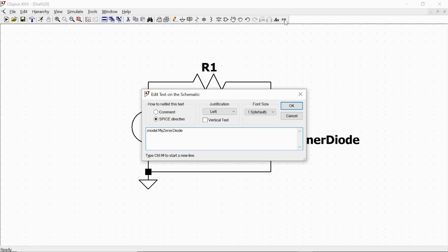The type of the component is the diode, so we say D. And then in between parentheses, we define the parameters of our diode. In some parts, they will be the same as the junction diode that you've seen in the previous tutorial. So for example, Ron equal 0, Roff equal 1 megaohm, Vfwd equal 0.7 volt, and now